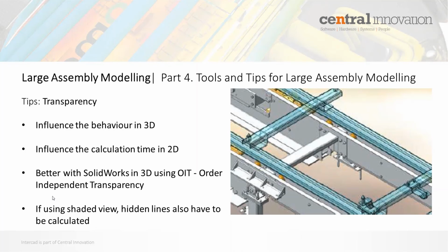Transparency in assemblies. They influence the behavior in 3D and influence calculation time in 2D, so on your drawing sheets. You get better performance with SolidWorks in 3D using order independent transparency.